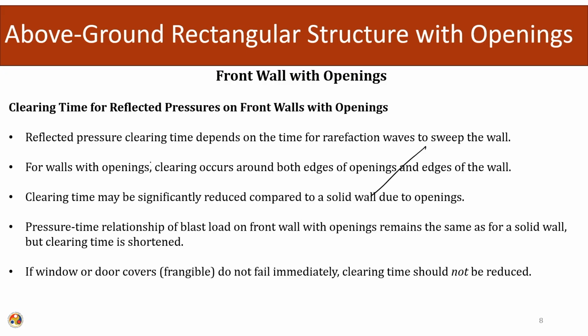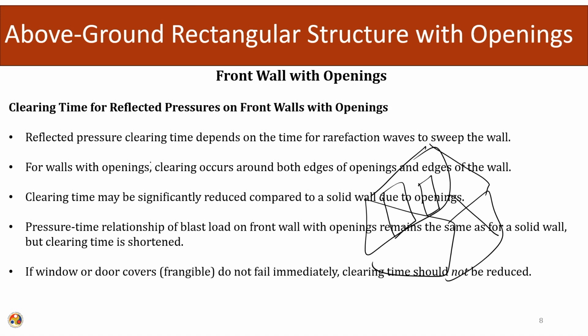Let us say we have a wall. In normal cases there is an actual opening, and this is behaving as a frangible element. In normal operating condition, this will behave as a solid wall, and during blast loading, if it reaches a certain peak critical value, then this becomes dismantled.